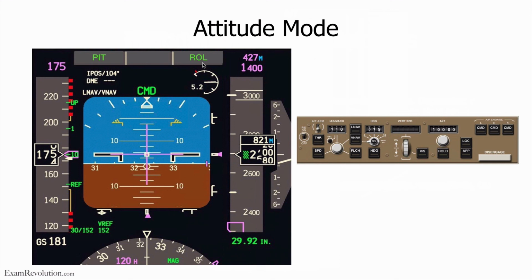So for instance, if you're trying to have the aircraft fly, if you give the aircraft two inputs on the autopilot panel, right, and it cannot comply with both the inputs, right, it will just revert to its basic modes, right. It will go back to pitch mode and roll mode, right. That's what the autopilot will do.